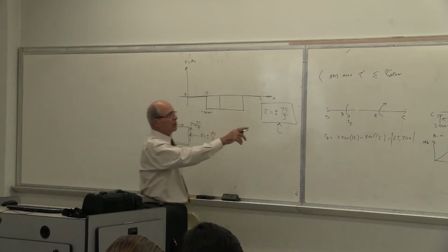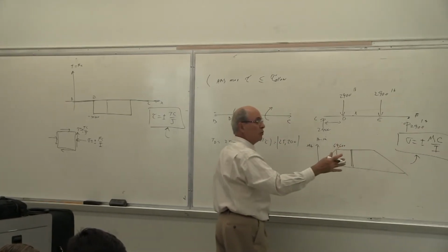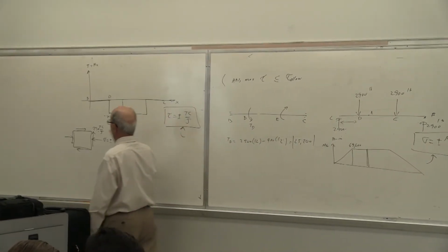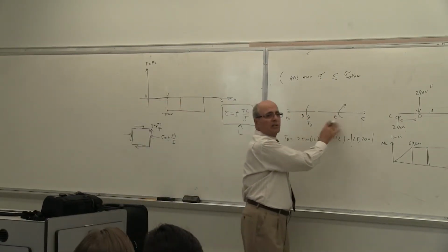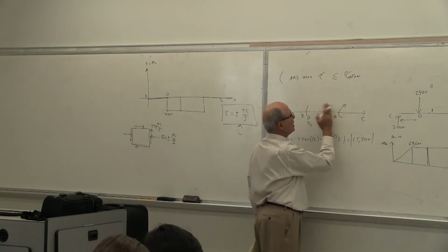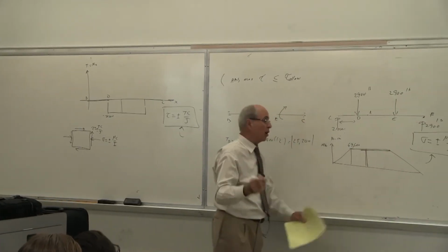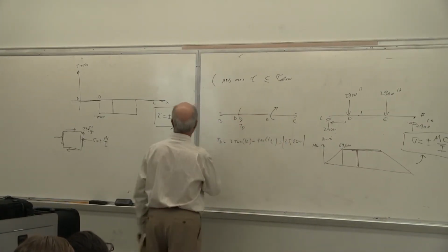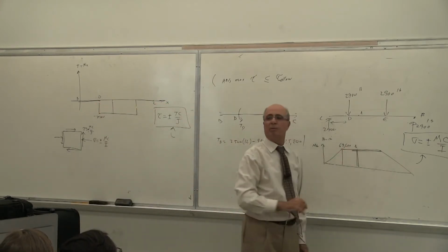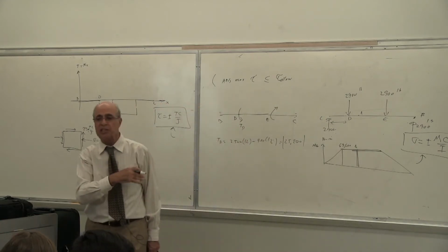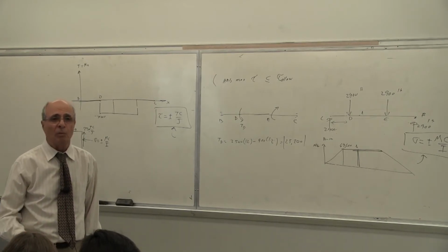This is step one. Look at what I'm doing. Step one, step two: when I want to calculate sigma, I need the size, but I didn't do the size. I bypassed that and came up to my stresses, the state of stress. The state of stress is somewhere between D to E. Is that correct? Because all are constant. For this problem, between D to E, everything is constant. Look, the moment ends up constant. This is not always true. And the torque, look at your diagram. Torque is constant and moment is constant. That's why I chose point A. Everybody understand? Because point A, any point between C to D will do. Is that correct or not? Yes? The same moment, the same torque.